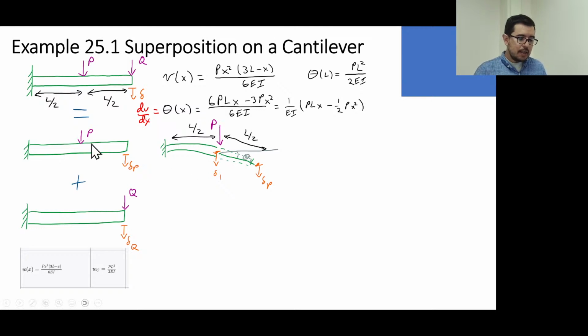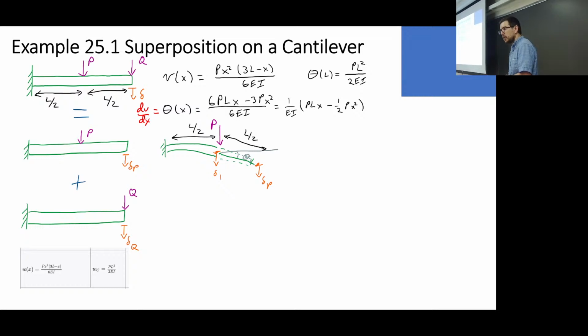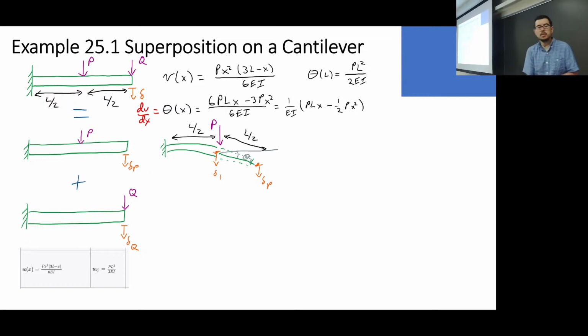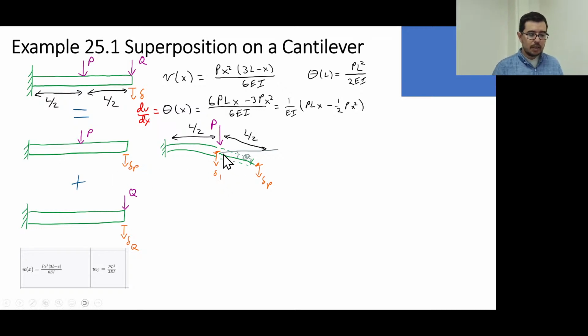Do you see that there's no shear force and no bending moment in this portion of the beam? Right here, if I take a slice here, there's nothing going on. No internal shear force, no internal bending moment. So what does that mean? That means, once again, that this portion of this beam is along for the ride.